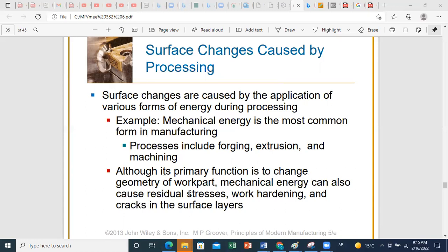If you remember when we studied the deformation, the variation of stress with epsilon, we said that if we exceed the elastic region and then we release the stress at a certain level in the plastic region, the material cannot go to the initial state. So we'll have a permanent deformation. We'll have what we call residual stresses. Sometimes we have residual stresses that are desired, and sometimes they are not, depending on the application.